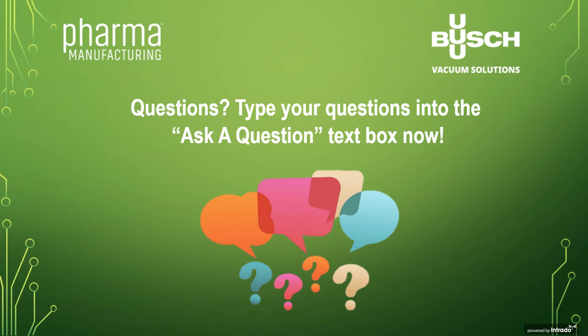Now, I do want to be careful because in a knockout pot, you also potentially have a filter and a demister pad that can get some of those fine particles out. A receiver wouldn't necessarily have that, and you could potentially have some water entrain and go through. But especially if we're just talking about slugs, the tangential flow would most likely knock most of that out, again depending on your pressures, flow, and the size of the receiver and how it's designed.